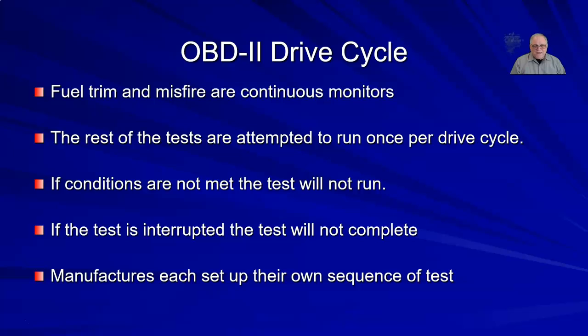If you're trying to get the test to run, drive it for about 15 minutes, shut the car off, wait 10 seconds, start it up, and try driving. If it didn't complete the test, it's probably not going to do it after about a 15-minute drive. And the manufacturers each have their own sequence of tests.